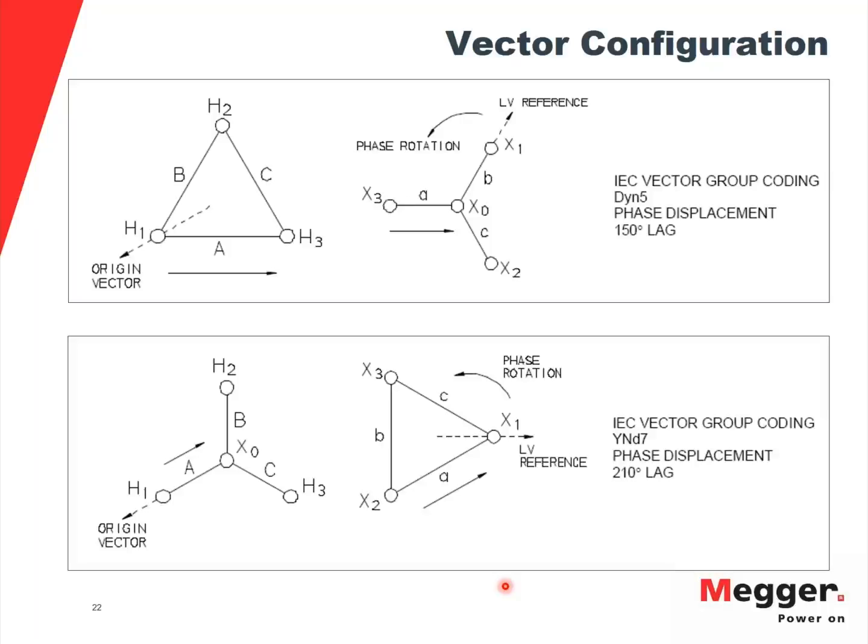So when you are first doing a test in the field, what I always do is a phase comparison to see if my A, B, and C phases are close to each other, because they should be relatively close and all at the same temperature, unless you're measuring one day and another day. Most likely you're doing all three at the same time, so temperature is taken out. So it's good to do a phase-to-phase comparison with the winding resistance. But if you're able to correct for temperature, then you can always compare to previous and factory results. Just make sure you're taking temperature into account.